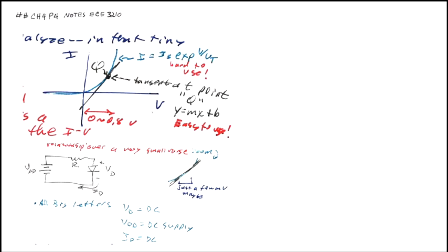So remember, there's this system. A big letter with a big subscript is a DC voltage. That's a voltage that doesn't change. I also call that a bias. If we have a big letter with two big subscripts, that's a DC supply: VDD, VCC, VSS, VEE. Those are all bias voltages that we apply, and they're expected not to change. They're DC. And we could have a DC diode current, some current that doesn't change, that's constant.